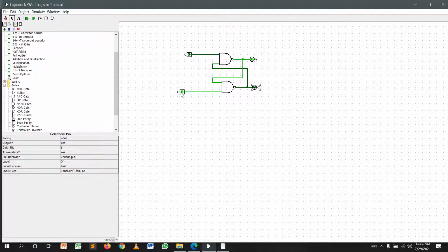When both values are 0, you can see both outputs are 1, but that's not a right value. If Q is 1, Q bar must be 0. Those two values must be different. So when we input 0 and 0 for an SR latch, this is an invalid condition.